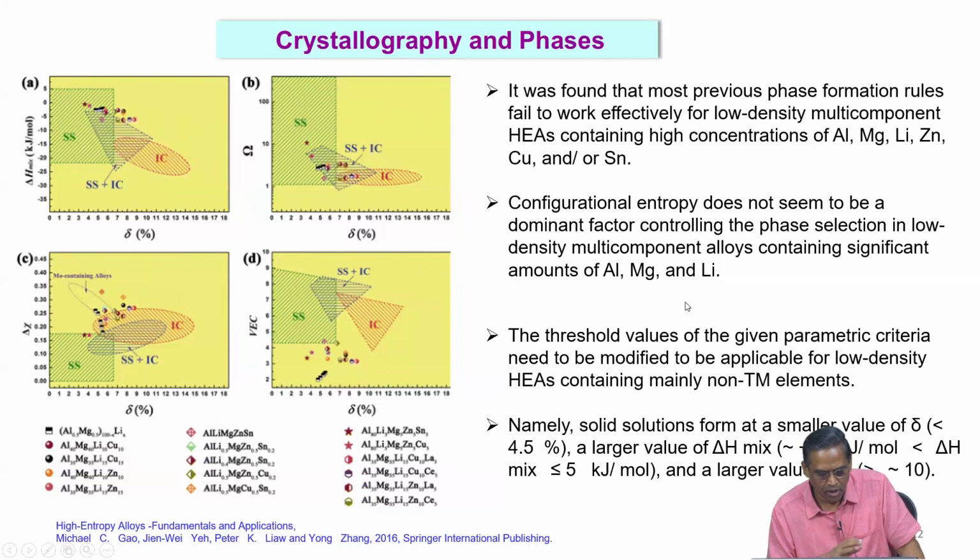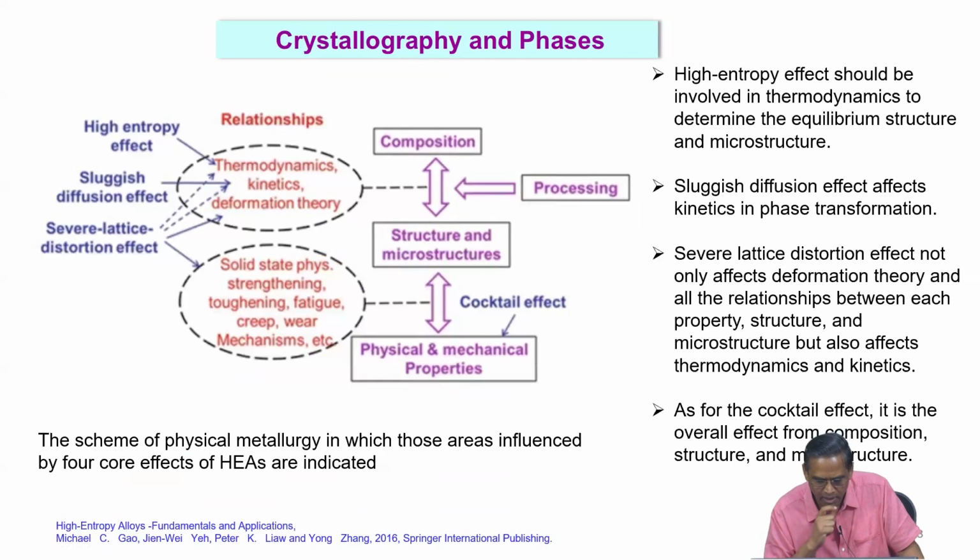So I will slowly now move to some of the basics of physical metallurgy idea of high entropy alloys. I hope that Gerhard had told you already about some core effects of these materials, something called core effects, right? High entropy effect, sluggish diffusion, lattice distortion, cocktail effect, and so on. Again, all these effects you have to keep with a question mark. These are all initial ideas people have observed and suspected, and then they have given some justification, but not all the systems are obeying this.